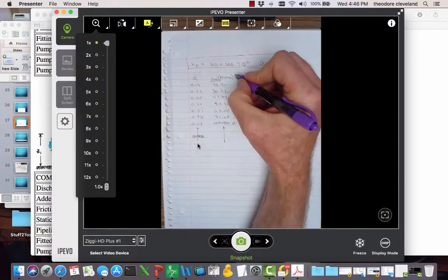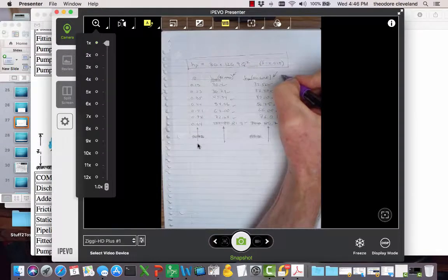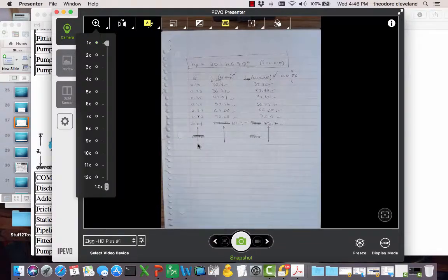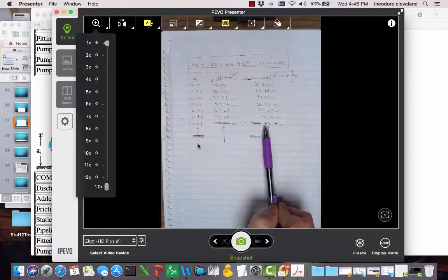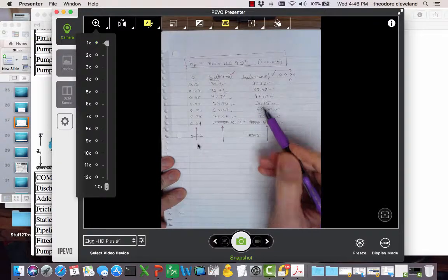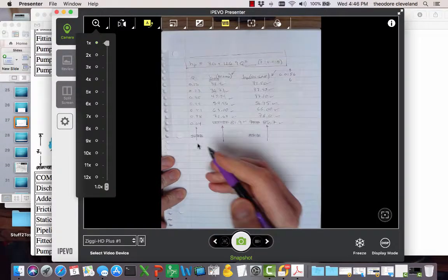Remember, this one had a constant friction factor, and this one had a friction factor that was 0.0156. It varied, but it hovered around there, and it correctly reflected that as the flow rates change, the friction factor changes slightly. They're not constants. The point being, all we had to specify for this was the geometric information, what the fluid was, and then by faking a series of pump curves, we're able to get the added head required by the system.